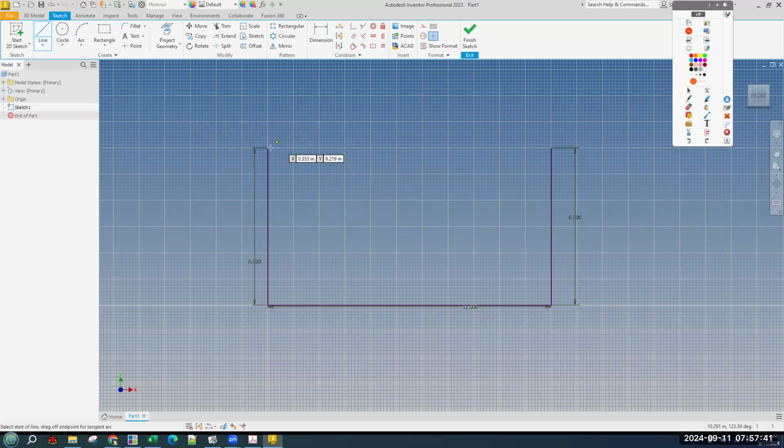So with the line tool, I'm going to click here to start, make sure it snaps to horizontal and whatever length, and then dimension tool, dimension this to 2, then line tool, and dimension this also to 2. Oh, I missed. See that it was not horizontal, and it's not going to work. Dimension tool, dimension, and dimension that to 2.